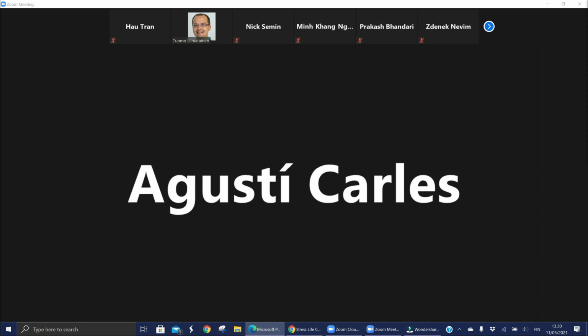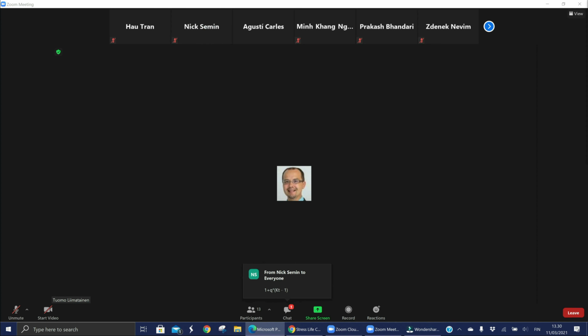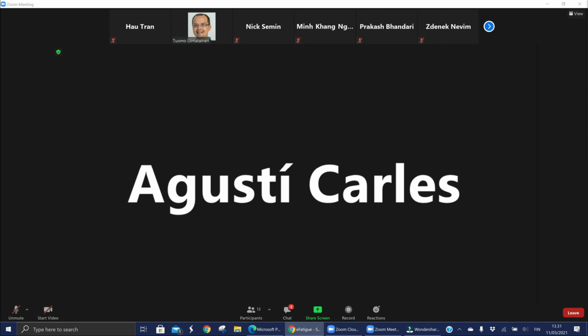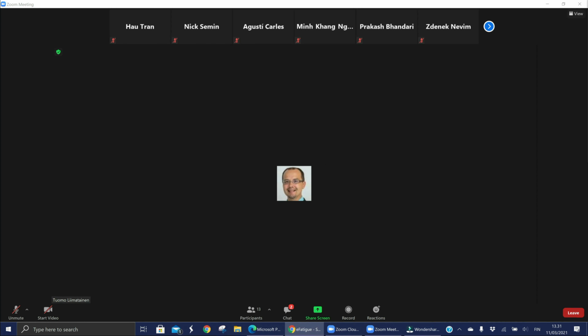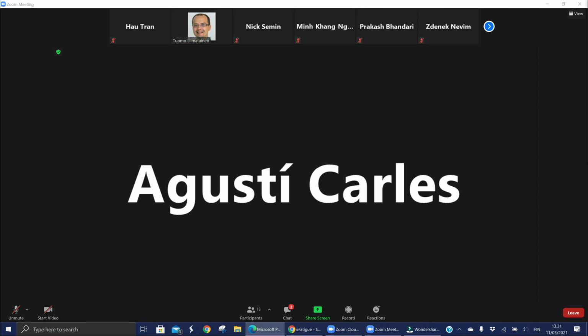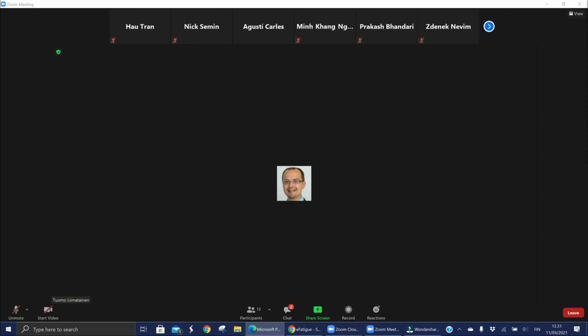So it's correct to say that beta is 0.1, more or less? Yeah, that's fairly close. I use 0.08, but if you use 0.1 instead, let's see. Yeah, it's so close. That's the reason I didn't know if you use the exact number or not. It has a slight effect, but in such a direction that if you use a smaller beta, you will eventually get a larger KF. So it's better if I use 0.08? Yeah, I think I've been using 0.08 for that.